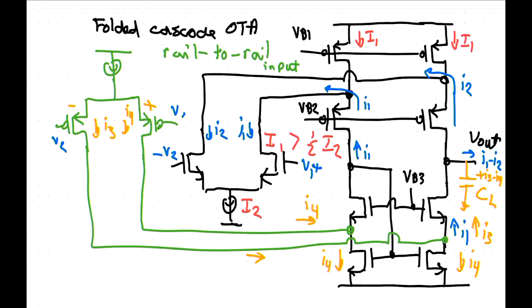For a small signal current, you need to have bias current going in it, so you need to have another current source up there somehow that keeps it going. But from a small signal point of view, you can get current in there. Yeah.